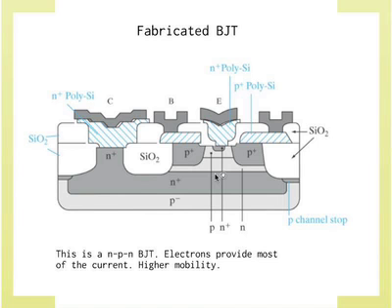In this case, electron injection current. Now, of course, the collector current collects that. Now, the base current provides the holes for recombination of the electrons in here, and also for the holes to go across this junction. Sorry, this forward bias junction. My mistake. Yes, go ahead.